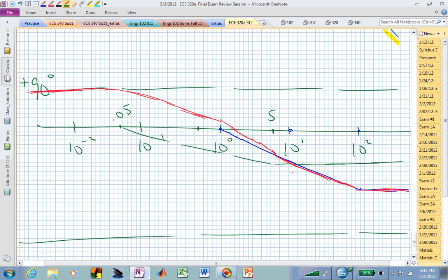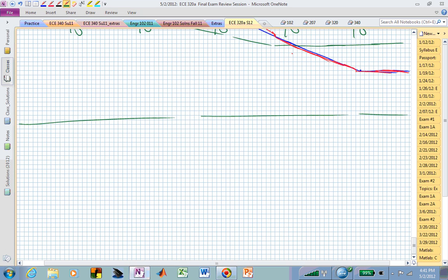So the question was, can you ever go above or below minus 180 or plus 180? You could answer your own question, I think. If I said something like, what if I have this? Now you say, what's happening at high frequencies? And what would be considered high frequency? Maybe a decade beyond the break. We only have 1 break, but we have 3 poles at that break. So let's say high frequency in this case would be 40 radians per second.